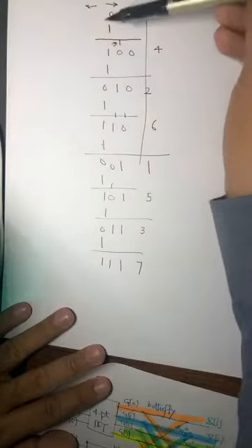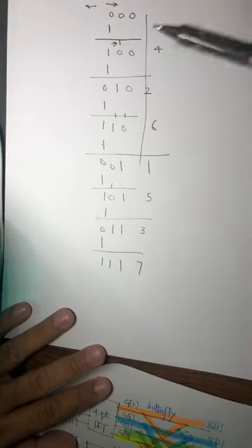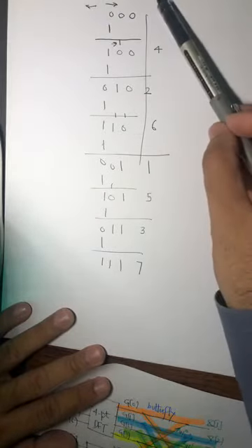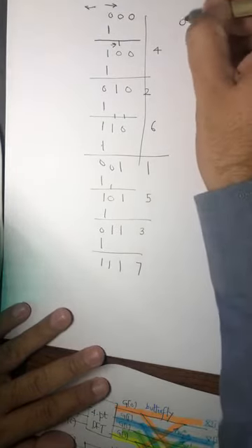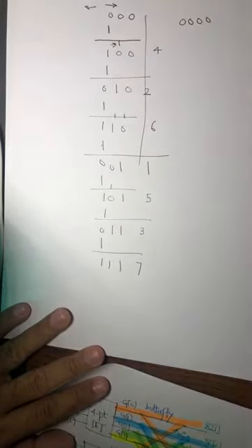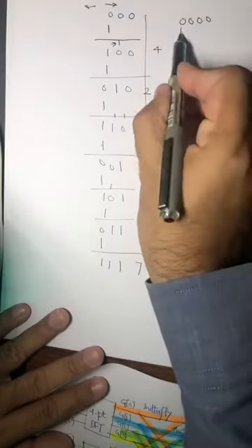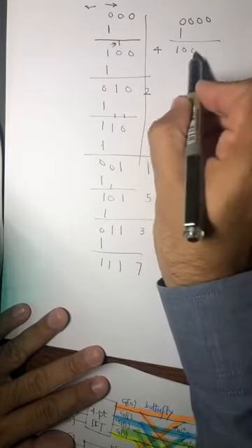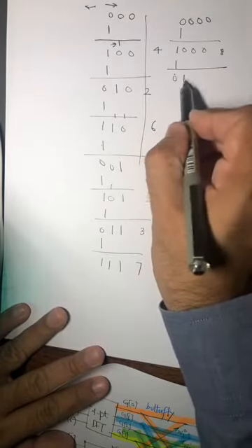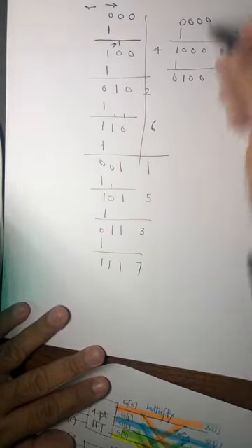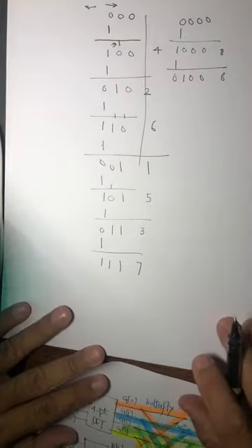So this generates the indices no matter whether it is 8 points or 16 points or 1024 points. This is for the 16 points. You add 1 here, you get 1, 0, 0, 0, which is 8. Then you add 1 here, it is 0, 1, 0, 0, which is 4. So you can generate all the indices.